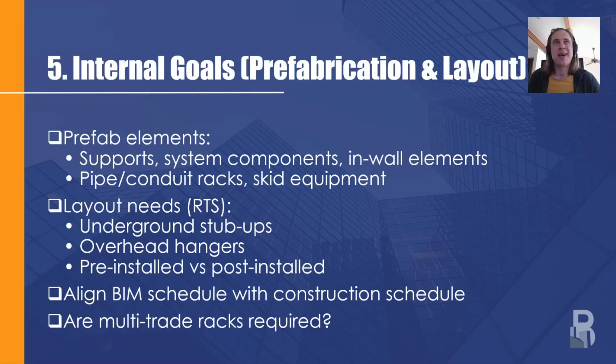Layout and means and methods for hanger installation can also impact the BIM coordination schedule. So your metal deck construction is fairly common. Concrete on metal deck construction is fairly common, I should say. So a lot of contractors like to get those anchors pre-installed, but prior to the concrete pour.